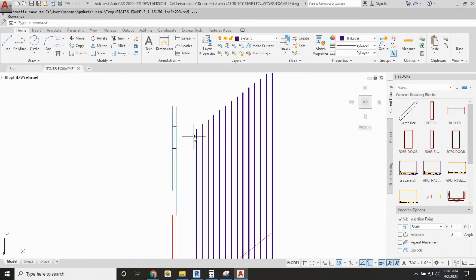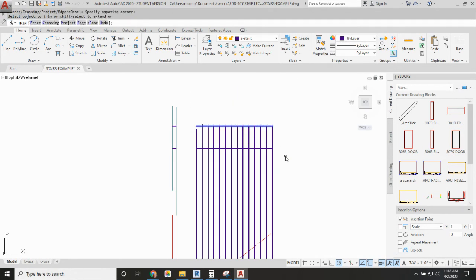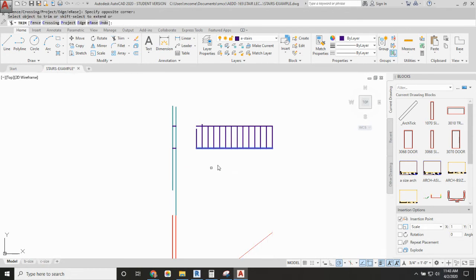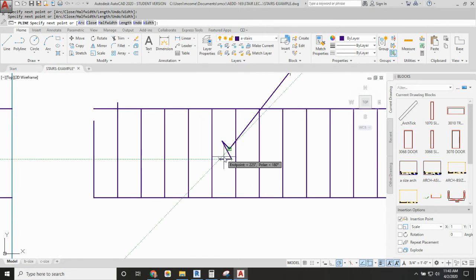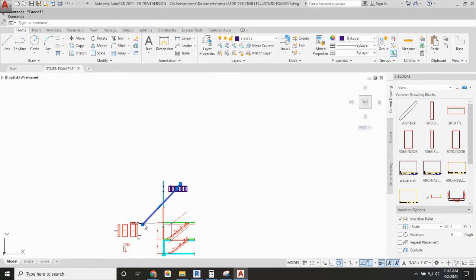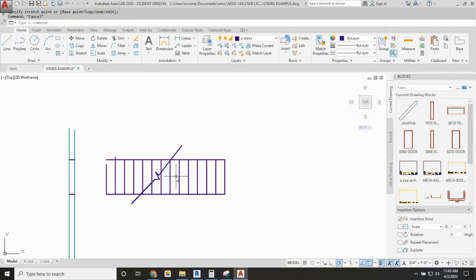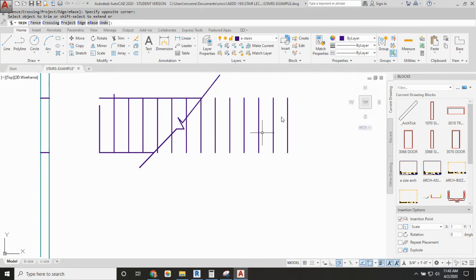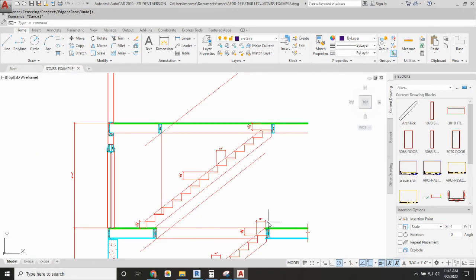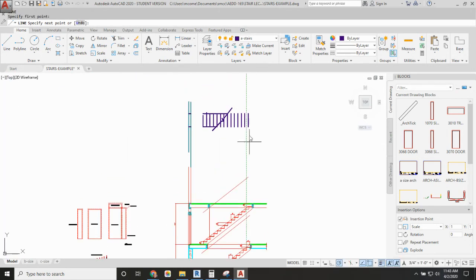So centered on that door, we're going to have the width of the stairs. And this is representing the inside width. So our stairs would be between these two lines here. And then we would put in a break line. Whoa, break line got really long, didn't it? So we put in a break line, and then this half of the stairs we'd project from the basement. So I'd trim that half. And let's see if we can just move these over by referencing where we are here. First tread should be here.